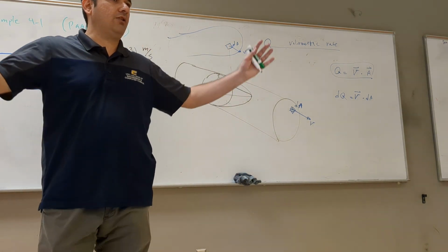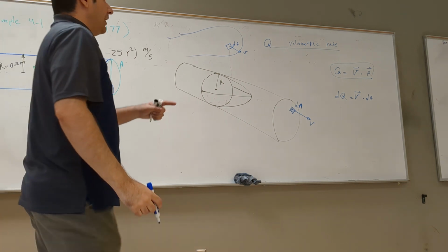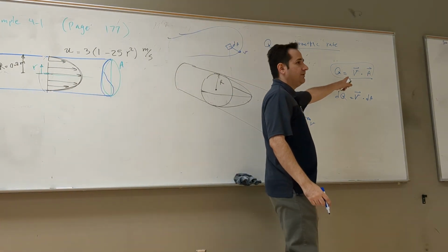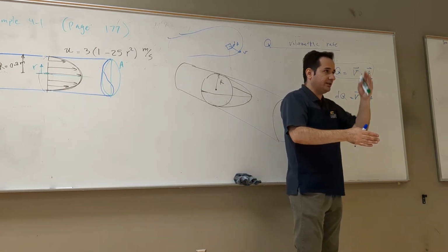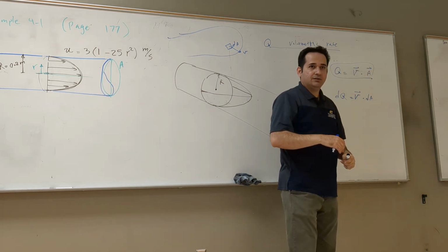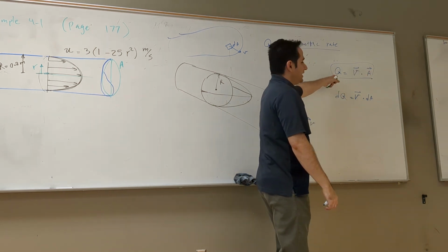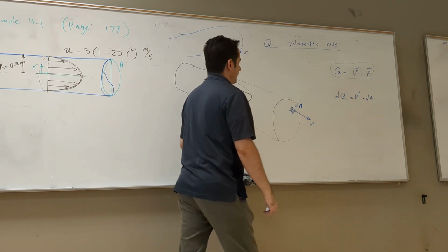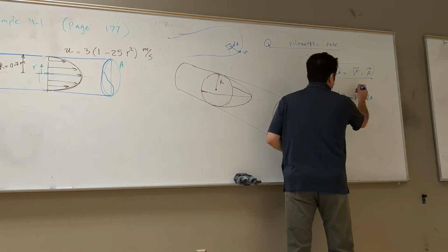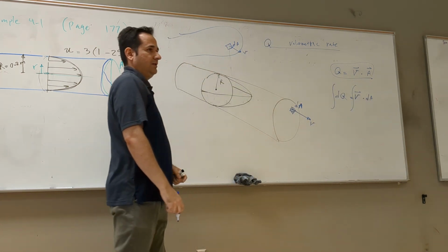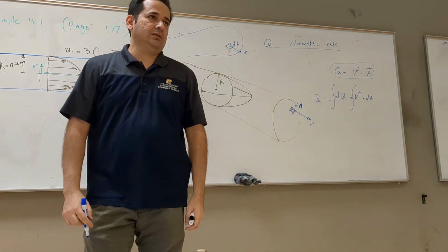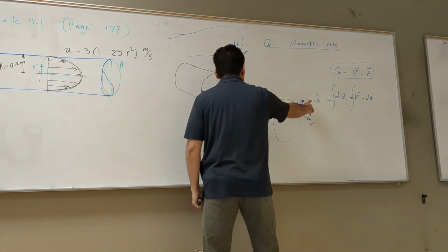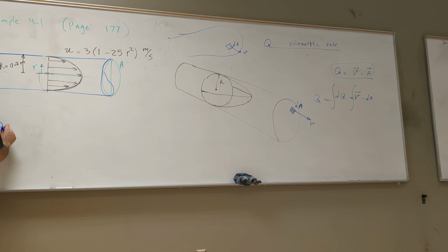And we derived the general form of continuity. Now you have to start from there. You can't start from the most simplified version, when your area was uniform, or the velocity. This is when the velocity is constant and the area is uniform. You don't have curvature. Right? So unfortunately, you can't start from here. You have to go back to the general form. But the general form was, you need to sum all those tiny elements on the surface to get your Q. That's it, because that's your stuff from here. Now, starting from here, you get Q is equal to the integral over the surface.